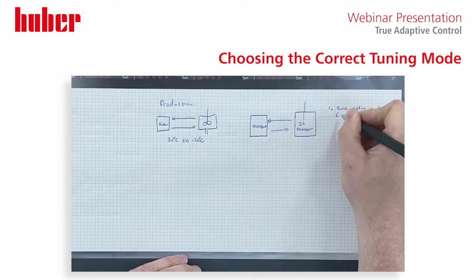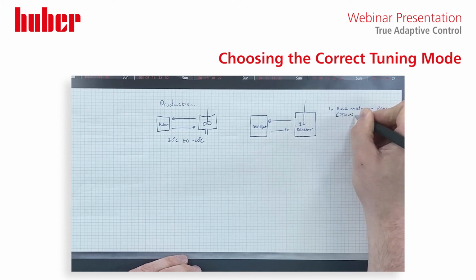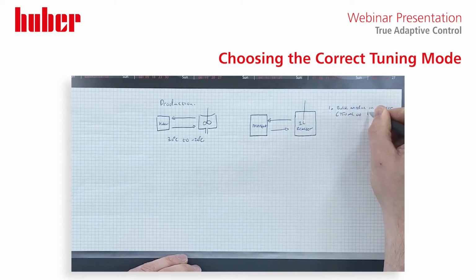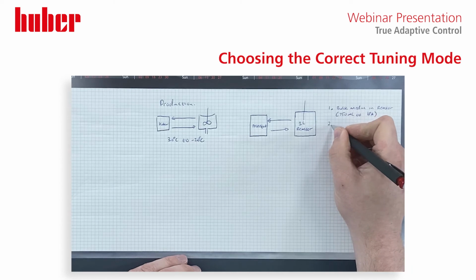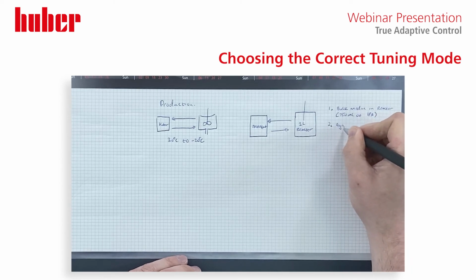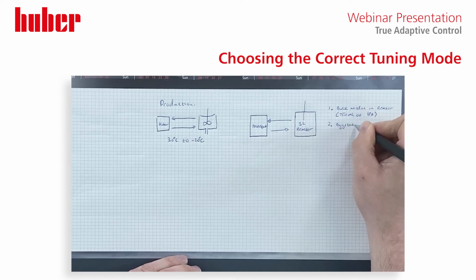So in this case, we have 750 ml of IPA. Number two, we need agitation. So here we're going to use our Radley's overhead motor, and we're going to go at 2,500 RPM.